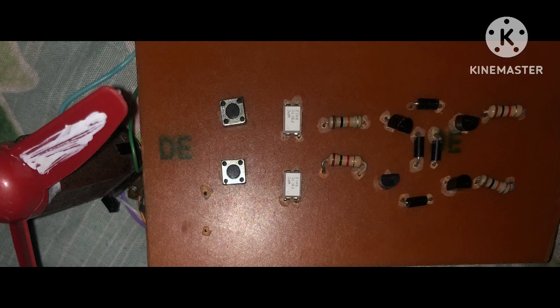In my circuit, I was facing one problem: two wires, the resistors a little bit, were connected by the optocoupler. They shorted, that's why my circuit was not working. Then I made some changes and kept the resistor away from the optocoupler. Then it started working, there was no short in the circuit, and the circuit was completely working.